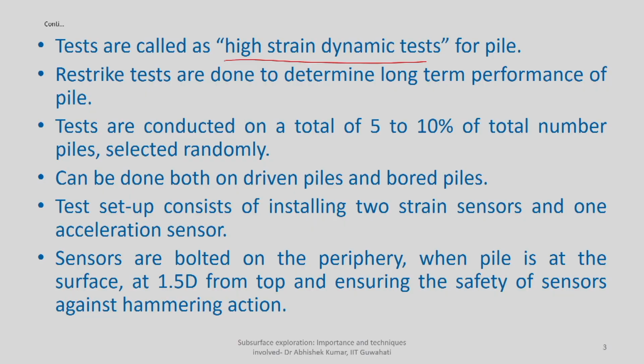The beauty of these tests is that you need not do any test separately. Anyway, you will be driving your pile into the soil, so you have to put some sensors. Based on the recording of those sensors, you will be able to understand the in situ characteristics of the pile medium. That will help you understand how much resistance the pile can offer against external loading. Similarly, you have the restrike test, which is done to understand the long term performance of the pile.